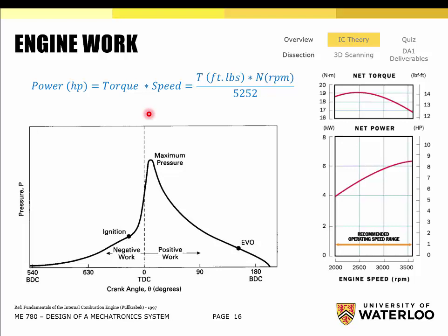Everything is correct except the fact that if you push directly down, you're not producing any torque at all. Imagine if you were on a bicycle and you had the pedals perfectly aligned up and down. What happens when you press down like that? Nothing. The pedal will just lock there and not move. If you're moving forward fast enough, there's enough inertia in the wheels rotating that it'll actually continue to move. But if you're stopped on a bicycle, you can stand on the pedals with your full body weight and it's not going to move.